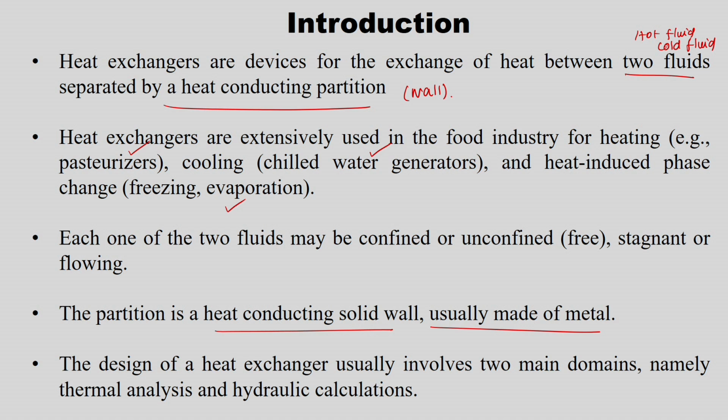The design of a heat exchanger usually involves two main domains, namely thermal analysis and hydraulic calculations, because in the heat exchanger the food is liquid food, right. So, if you remember in our aseptic processing calculations, I told the same thing, because in continuous thermal processing we need to take care of the hydraulic calculations as well as the thermal analysis, heat transfer as well as fluid flow.